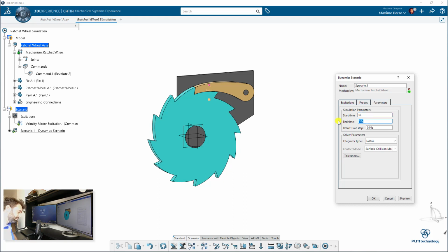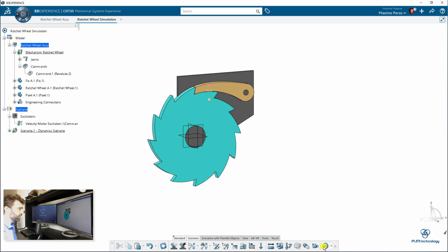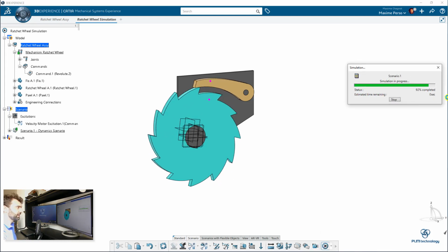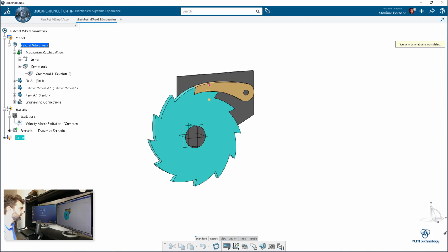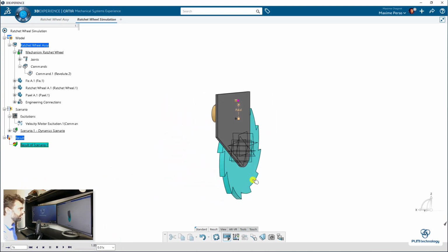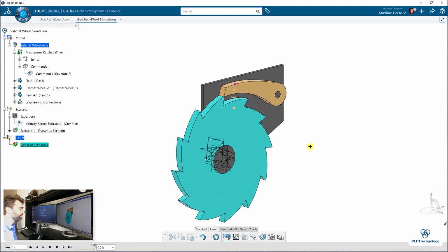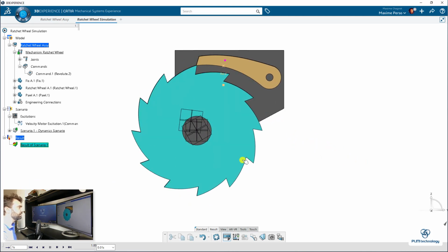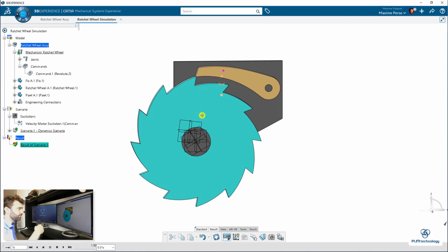Remember, when you do a simulation, you select something small because it can take a bit of time. So we will select also Symplectic Euler. Okay, we should be good so far. We do the simulation, it's turning. Great, quite fast, but it's turning. That's not bad. You can always replay the dynamic simulation a bit, and I like that I can turn it while playing. So in that case, it's working. Clearly, the pole is working, the spring is working as well, because it's coming back to the wheel. So we validated that part at least.